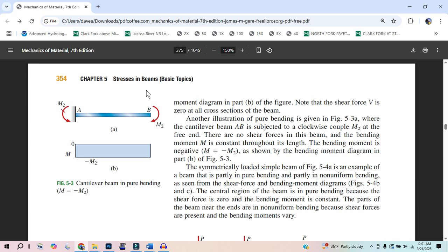If we have this little slice, we know that this moment is going that way, and we're going to draw this one in positively. But this one's causing it to spin this way. A positive moment would cause it to spin more, so this moment over here has to be negative. The opposite is true. You don't have to label this in this direction either.